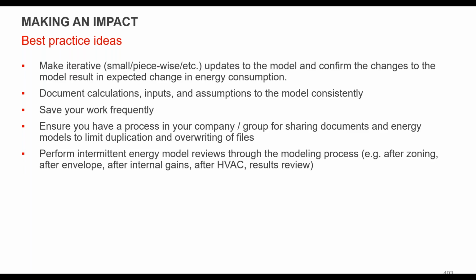And then in terms of doing reviews, and this is something we hold really tightly in-house at Code Green, we review multiple times on a single model. So you're not just getting a completed model at the end of the day and doing a full review of every system. You're checking in periodically to make sure the model's going in the right direction. Make sure you're checking zoning, envelope, gains, HVAC along the way, so that when you get to the final model and you're comparing energy to energy between the proposed and a baseline, you don't have to go back and re-review all these individual components. You've already reviewed them, you've checked them off.